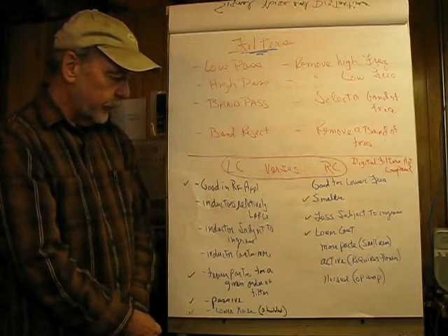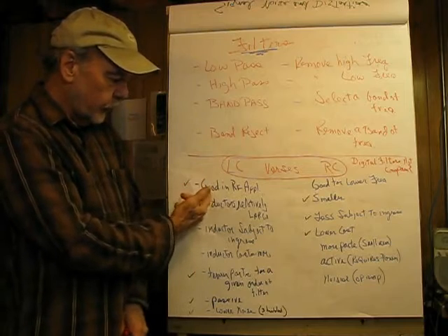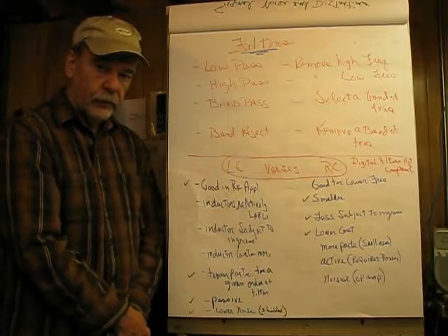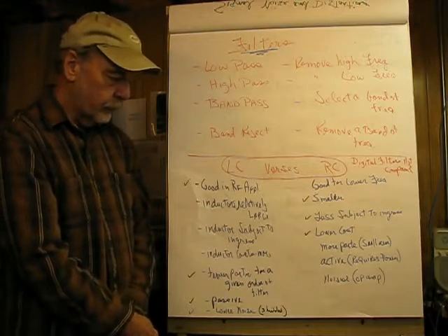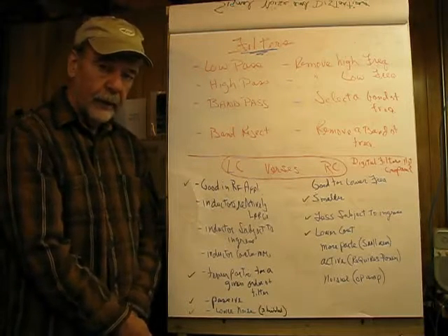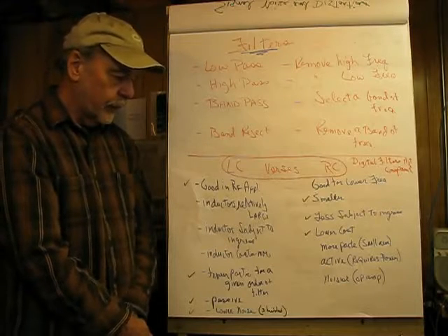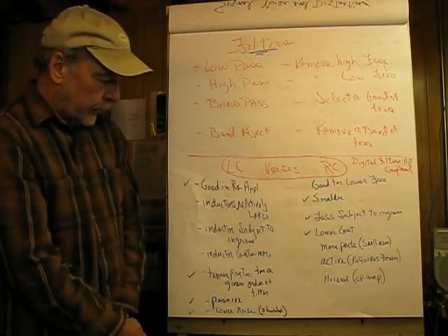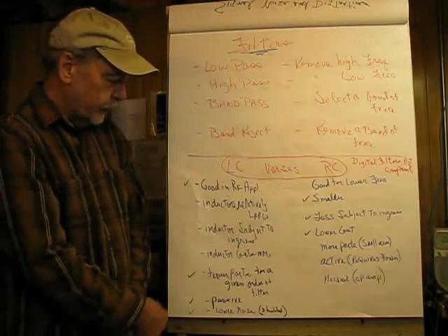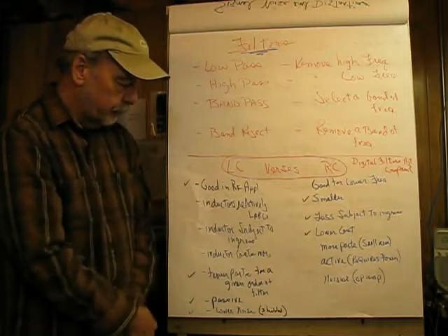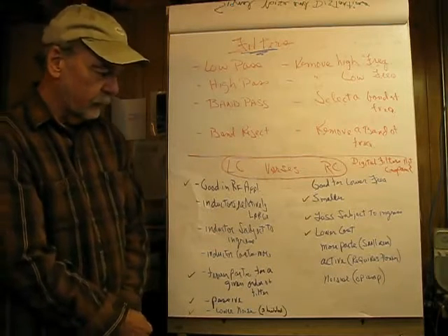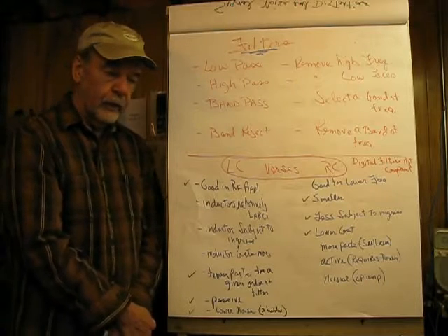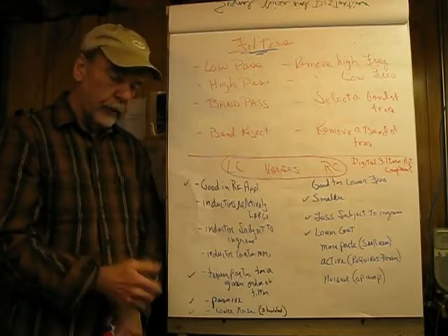So for using an inductor or a capacitor here, what we have is LC circuits are good in RF applications, where operational amplifiers would be hard pressed to operate at some of the frequencies that we're going to be seeing, or expensive. And a kind of bad thing is inductors are relatively large compared to capacitors and resistors, so that would take up more printed circuit board real estate.